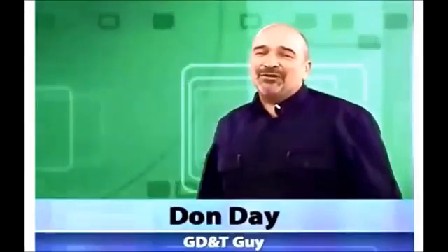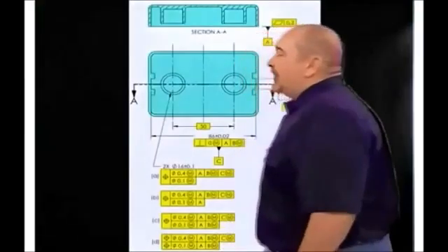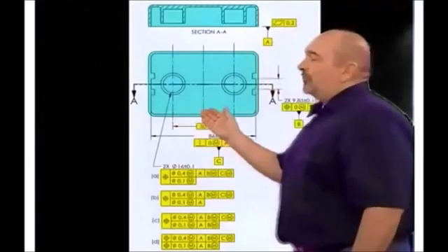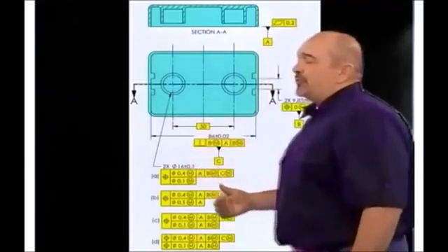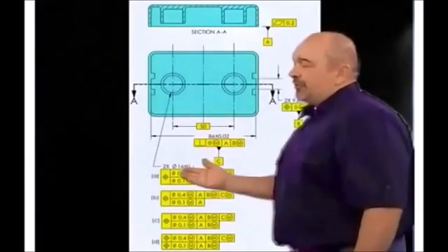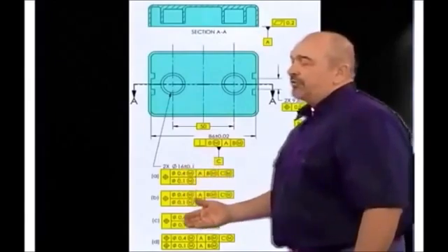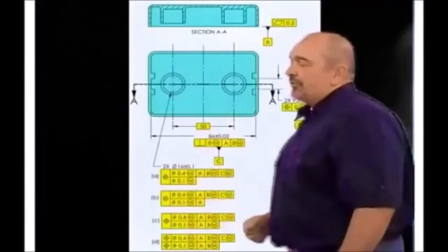A lot of people remain confused over the differences between composite and two single segments. So to help clear it up, I created a drawing. On this drawing, I have a pattern of two holes. And I've shown four possible geometric controls. The first three are composite. Notice there's only one position symbol. The last one is two single segments.